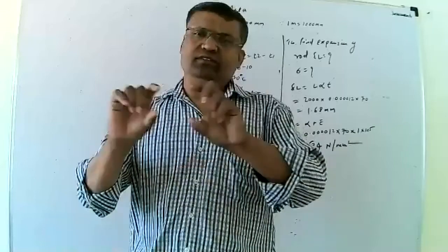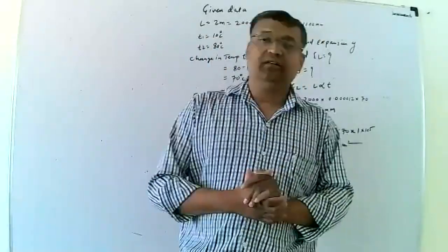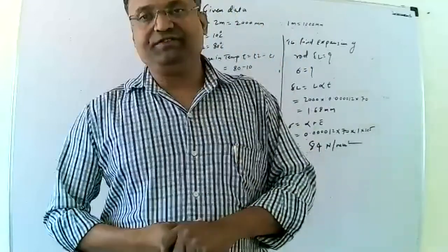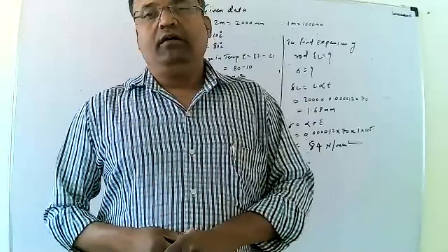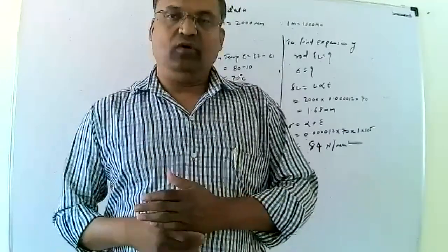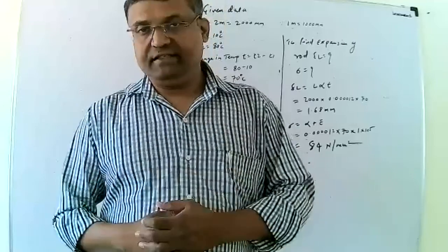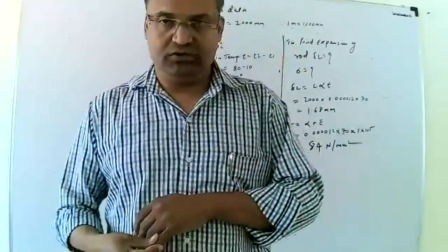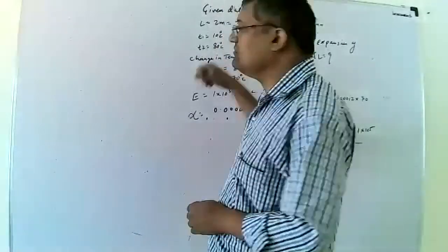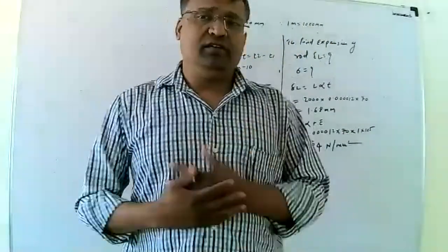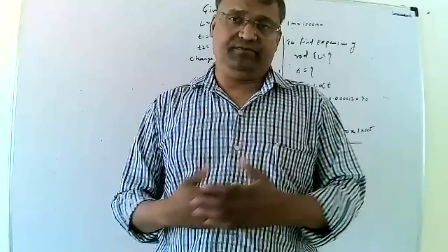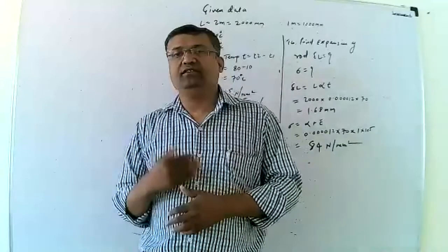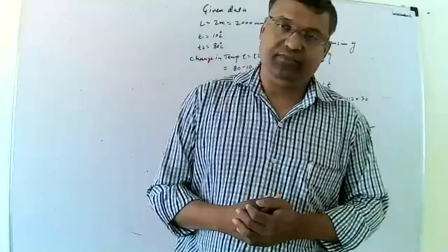A very simple way: suppose a specimen is provided in the problem having a length of 2 meter. Both ends of the specimen are fixed. If the initial temperature of the specimen is 10 degrees Celsius, then it will rise up to 80 degrees Celsius. Then what will be the elongation of that specimen, as well as how much stress will be generated.